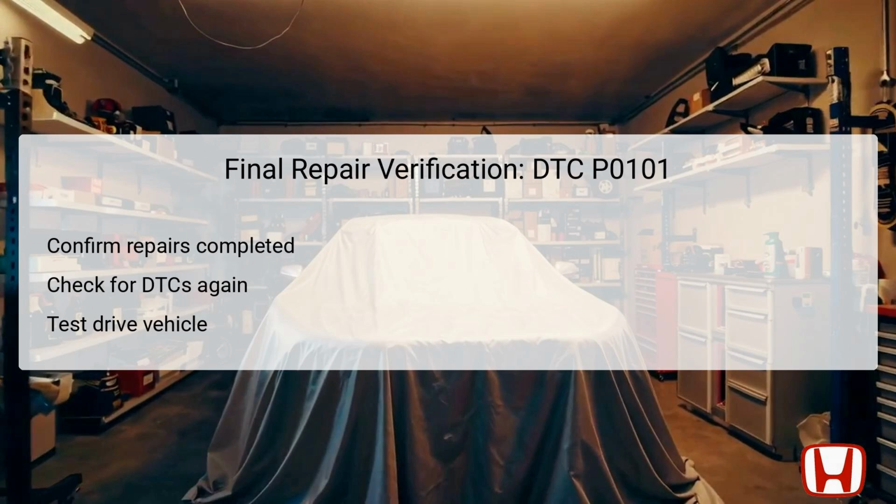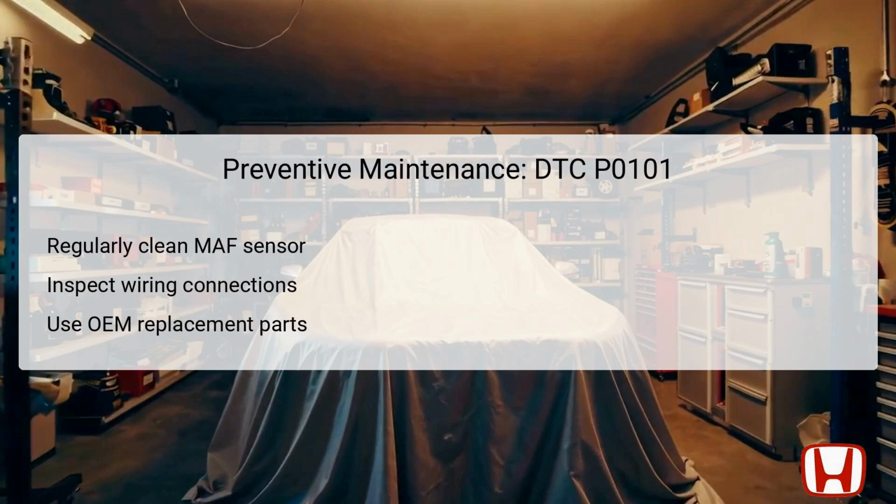Preventive maintenance is essential for sustaining the performance of the MAF and IAT sensors. Regularly cleaning the MAF sensor can help prevent dirt and debris buildup, which could impede its sensitivity and accuracy over time. Additionally, it is advisable to routinely inspect wiring connections for signs of wear, corrosion, or loose terminals, which can contribute to sensor issues.